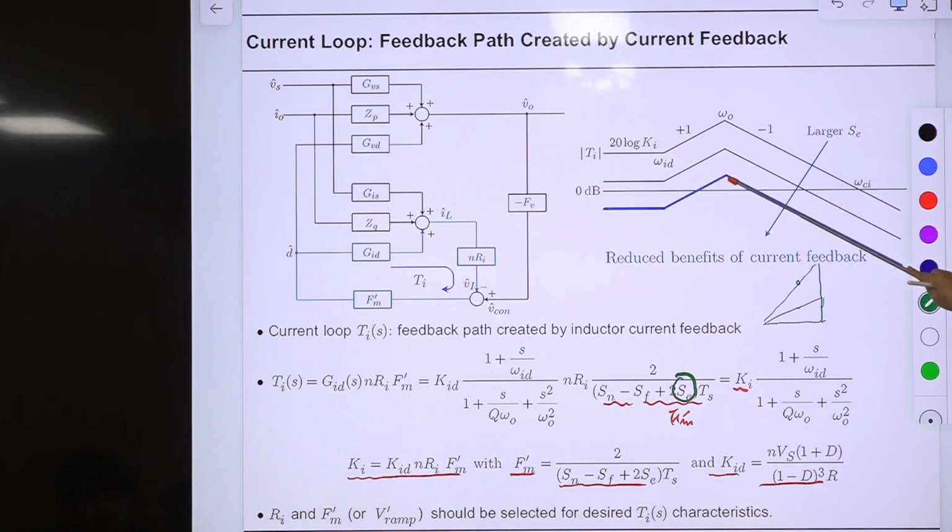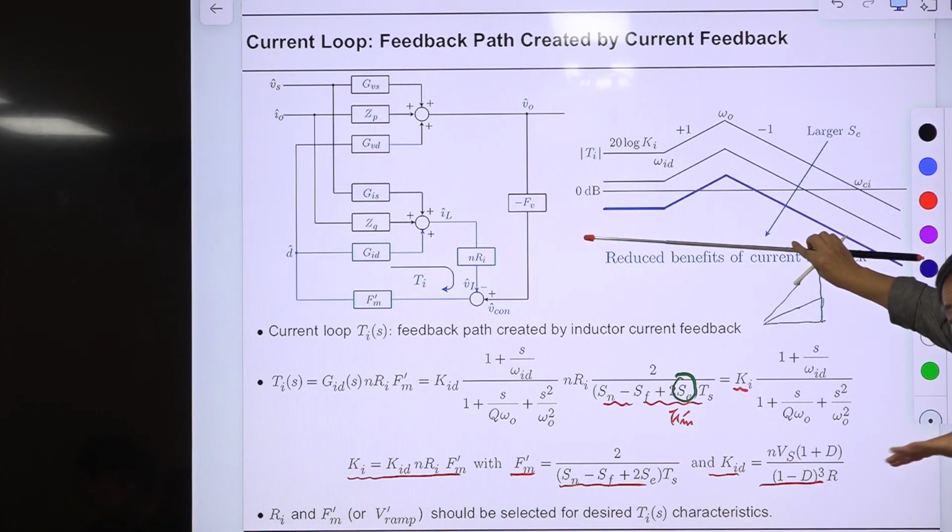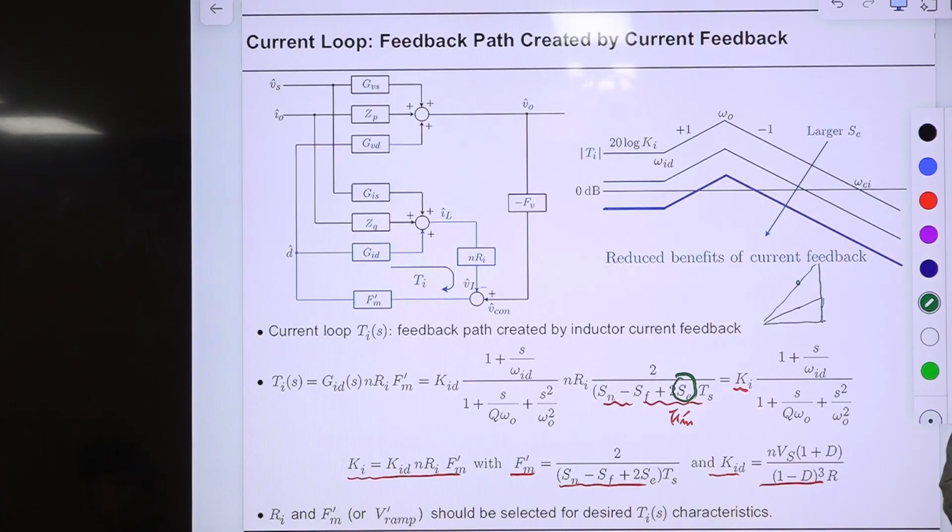The only remaining part is this. If it goes below this one, it entirely sinks down. Then you have the shape, structure and circuit components of current mode control, but you are doing it just the same as voltage mode control. So the benefit of current feedback is reduced, and current feedback will be gone if you increase this. So selecting this one is the only design option.